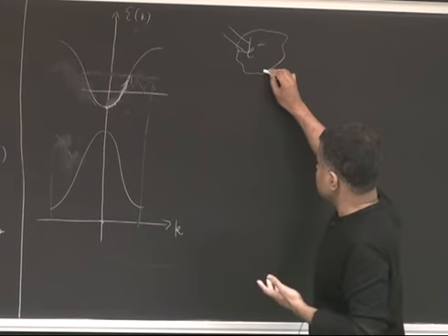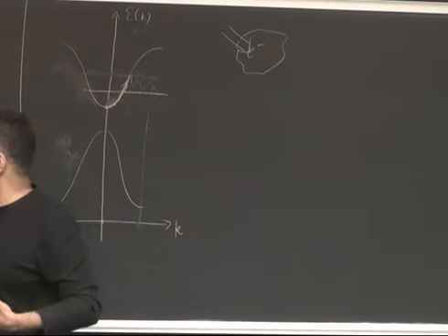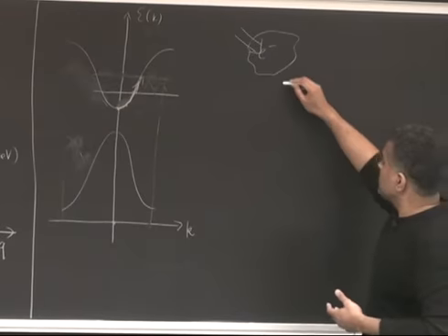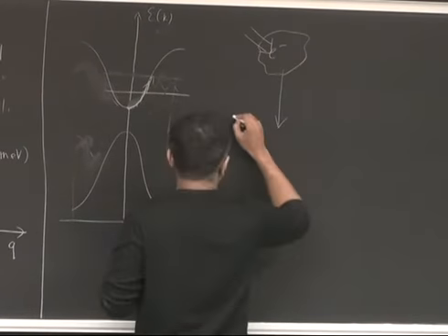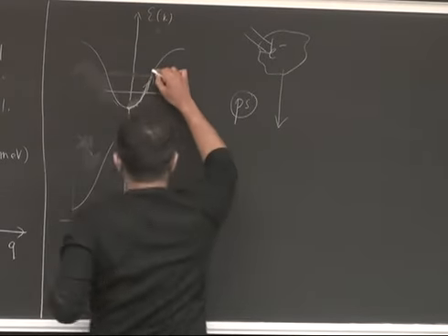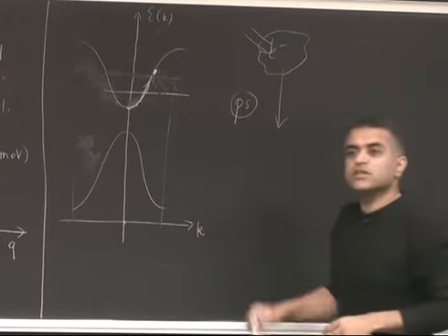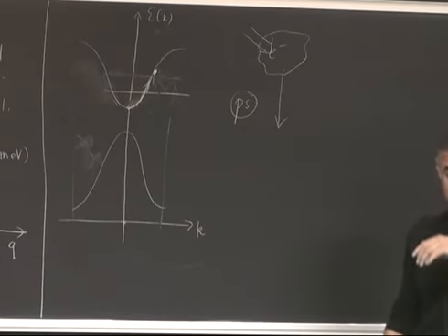But then there are certain time scales for emission of acoustic phonons and certain time scales for the emission of optical phonons. So in typical compound semiconductors, the optical phonon emission rate would be of the order, meaning I'm qualitatively drawing this picture, of picoseconds is how long it takes. If at t equal to 0 you start the electric field and electrons start accelerating, and it stays at a high energy state, it's feasible for it to emit an optical phonon, but it needs at least a picosecond to do that. That's the time scale, and this comes from golden rule evaluation. So I'm not deriving it. So about a picosecond. Right?